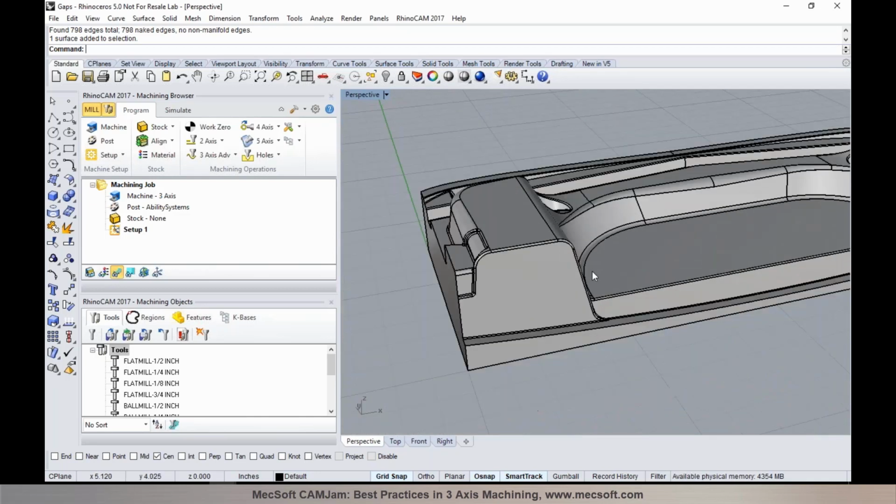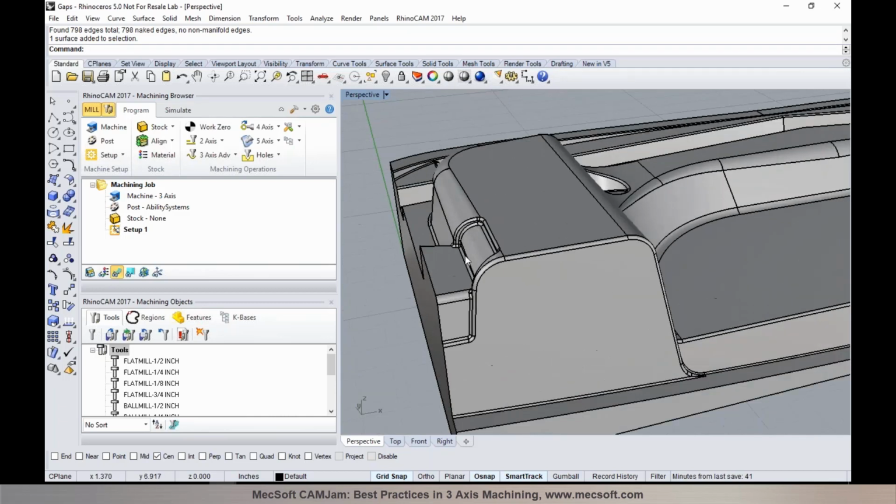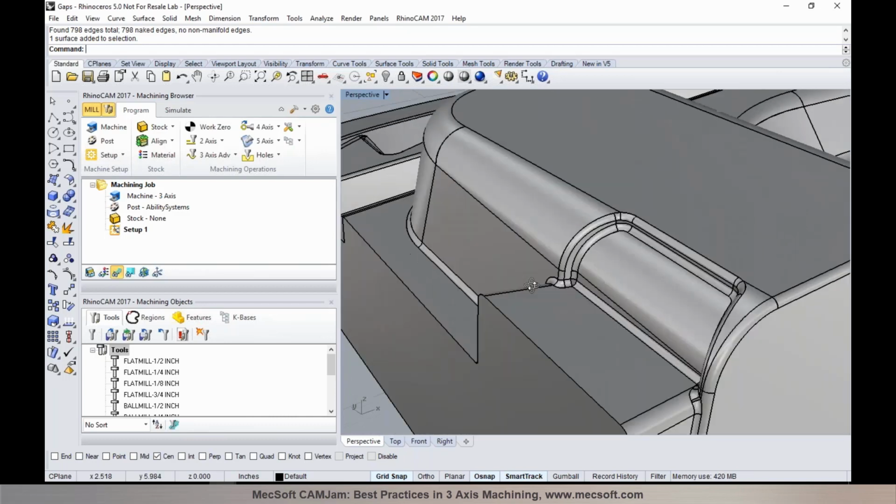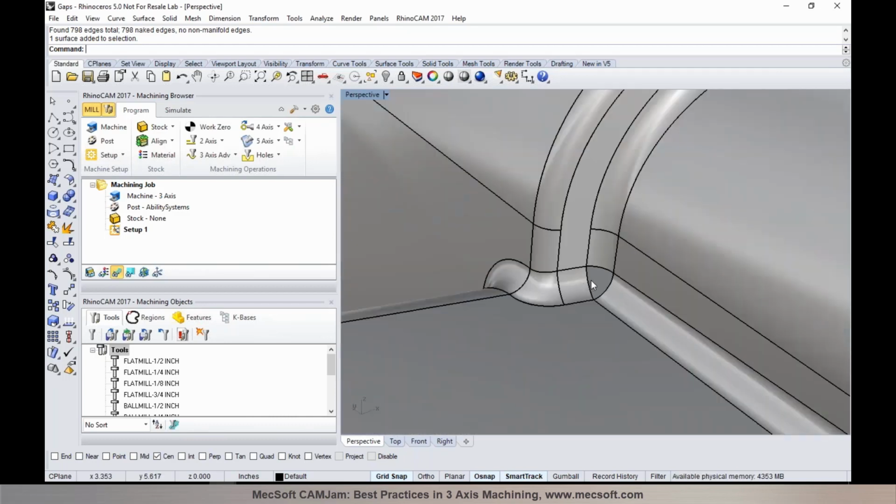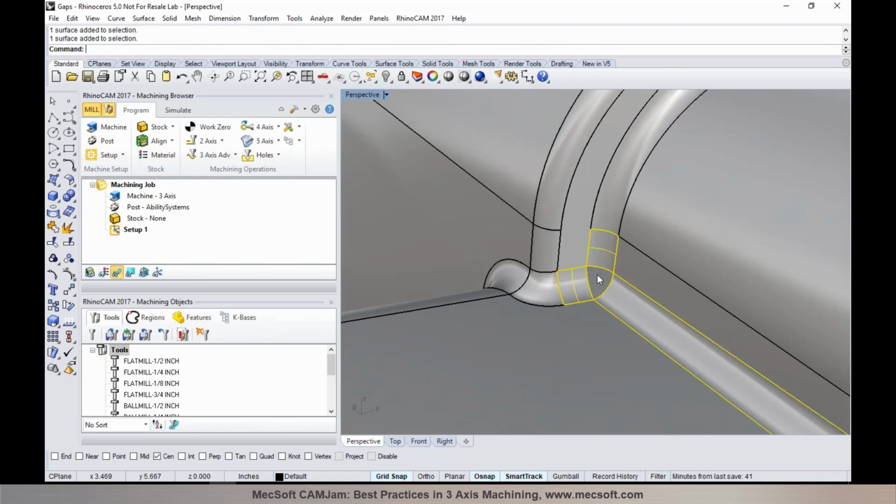So let me interrupt here, Uday. As far as the gaps, you can think of the problems associated with machining. When you have such a large gap, like a fillet or an end fillet missing, the danger is it's so tiny that you miss it, and you run the machining operation. The machining operation will work fine, but if you're using a small enough tool, the tool could potentially go into that hole and down to the bottom surface, and then you have a lot of problems. That's your catastrophic or pathological case.